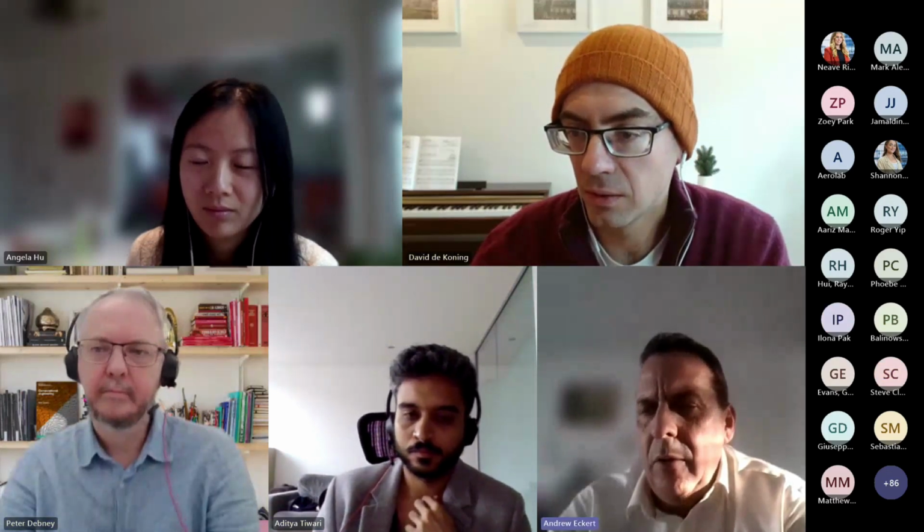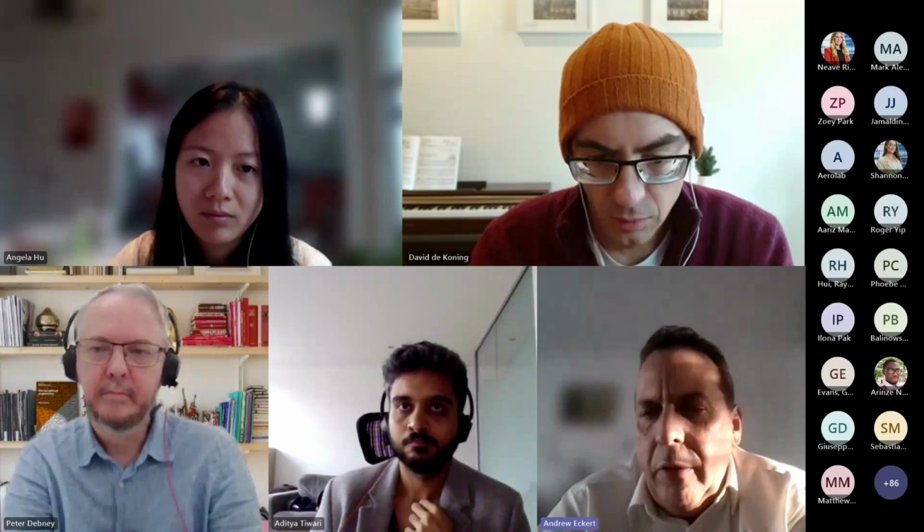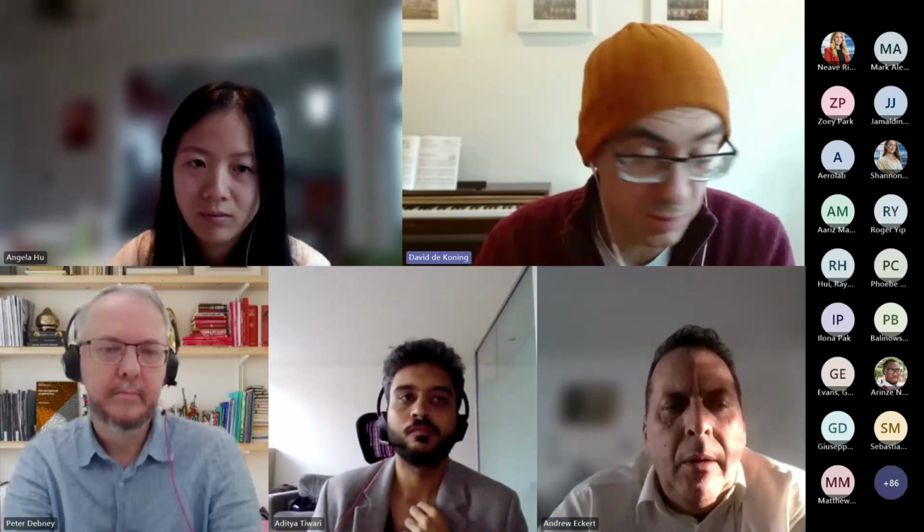Okay, and then what looks like the final question. They're asking if there's a specific module just for timber engineering, or whether you would use GSA for all of your timber engineering. Yeah. So GSA has been used for a large amount of timber engineering. We are currently looking in particular to tie into our strength and footfall analysis to make it easier to model CLT slabs and do a footfall analysis of CLT, especially since cross-laminated timber floor systems are very often vibration controlled. So that's something that we're looking at in the next little while. But at the moment, we don't have a one-click timber design.